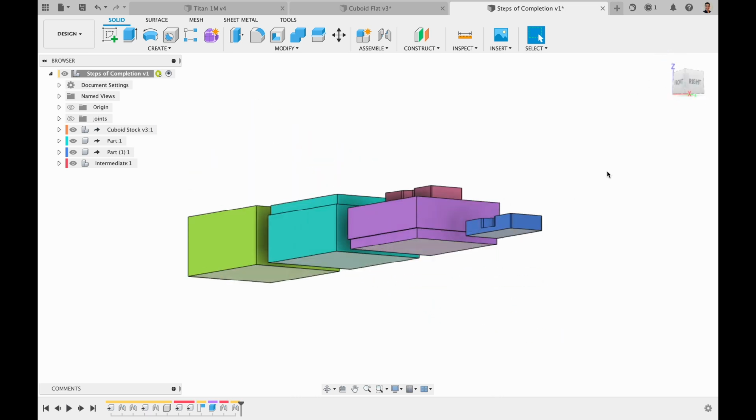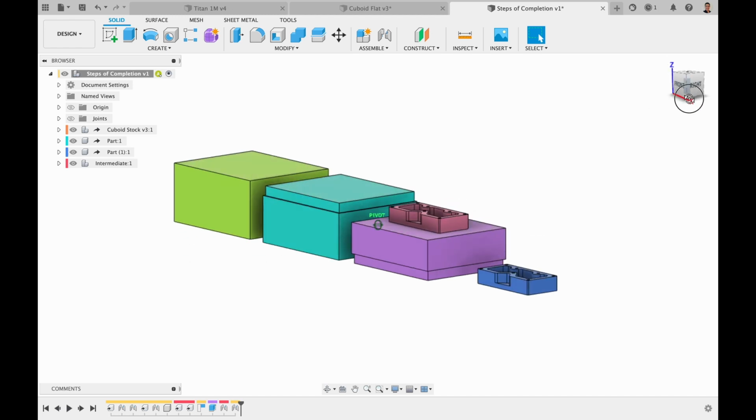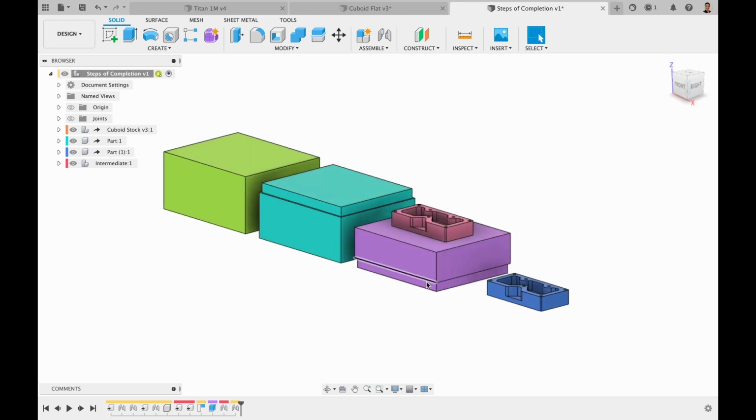The bottom portion cannot be accessed. Furthermore, we still need material to just hold on to the part. Once we have done this side, we flip it around and machine off the back and get our final result. These are the different steps it takes before we have a fully finished part.